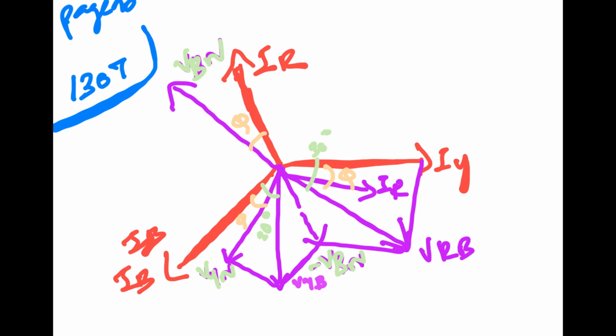We cannot strictly define the power factor in three-phase unbalanced circuits, as every phase has a separate power factor. The two wattmeter method, when applied to measure power in a three-phase balanced circuit, provides information to calculate the power factor of the load. Vector diagram explanation continues. Now consider the readings of the two wattmeters in the figure.